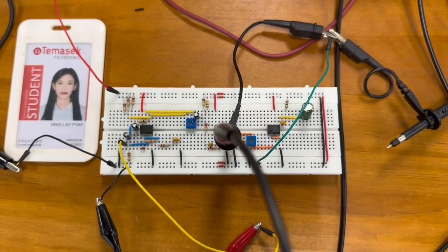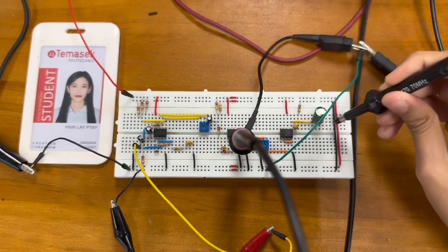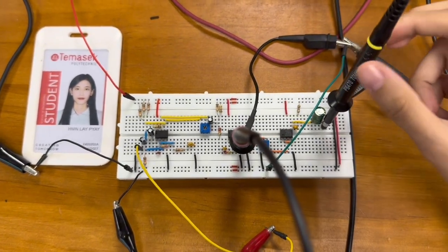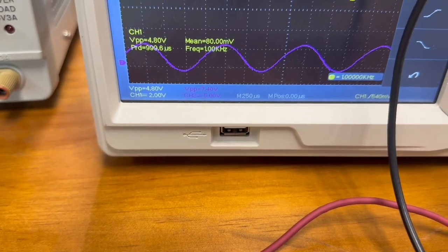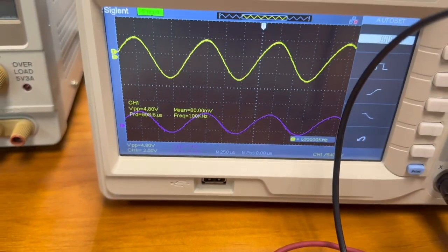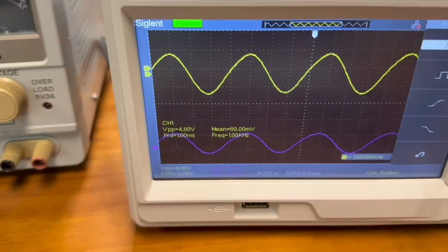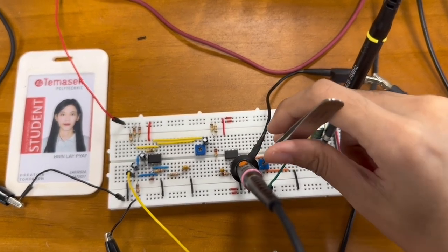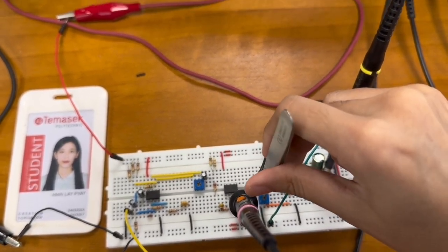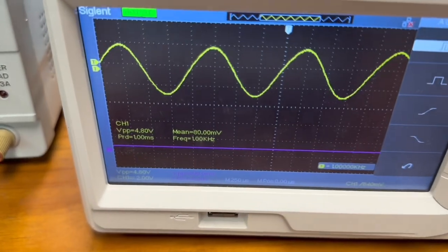To set up stage 4, we will do the same as earlier by keeping TP4 at channel 1 and all else untouched. We will then place the channel 2 probe of the oscilloscope to TP5, then we get an output voltage of around 7 volt. By adjusting trimmer P2, we can control the output at TP5. Final output is maximum as a sine wave attained without being saturated.